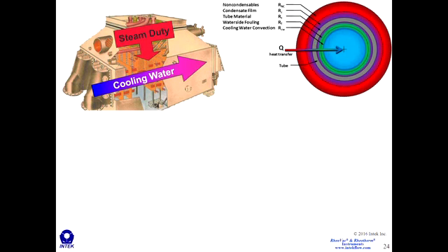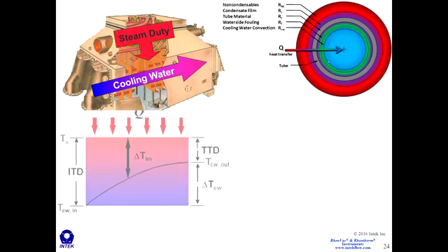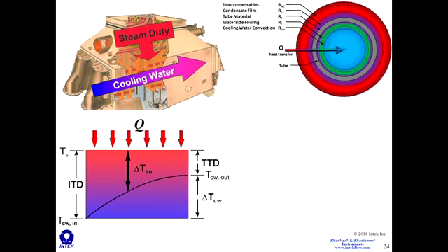And so there's a thermal impedance to heat transfer through that layer. And then you have another impedance determined by Nusselt type equations, and that's the convective heat transfer through the water from the inner layer of the tube or fouling to the cold cooling water. And so those are the thermal impedances that are seen in this heat transfer process from steam to cooling water through the tube and all of the thermal impedance layers between them.